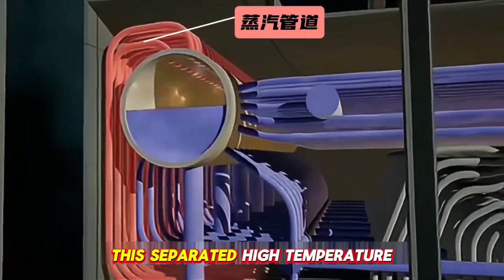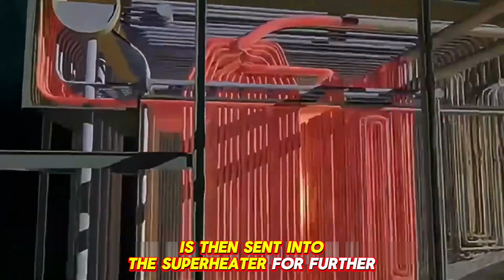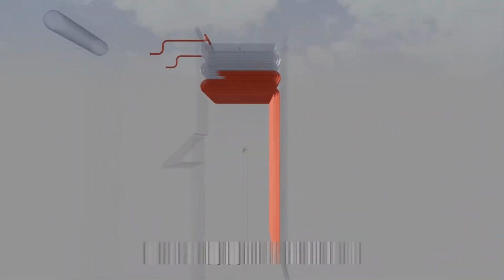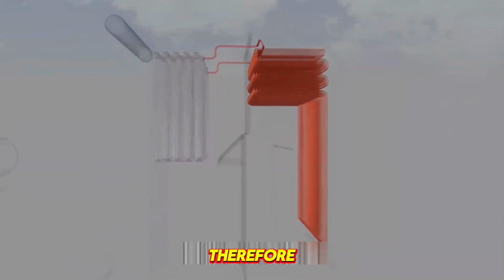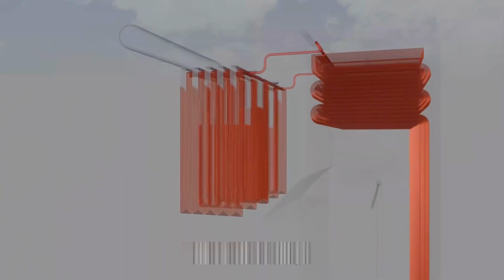This separated, high-temperature, high-pressure steam is then sent into the superheater for further heating. Here, the steam will gradually transition from a saturated state to a superheated state. However, the steam's temperature is still not high enough. Therefore, the steam is then sent into a second superheater for continued heating.